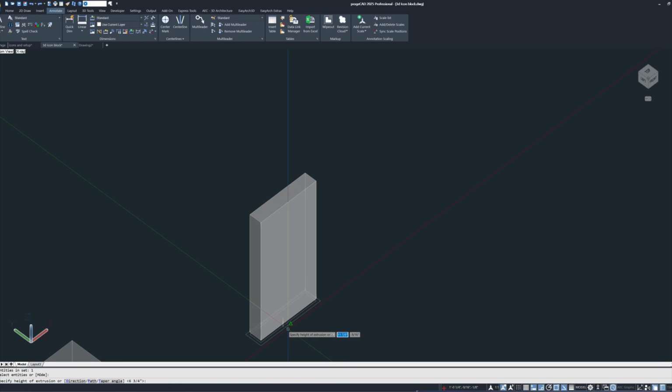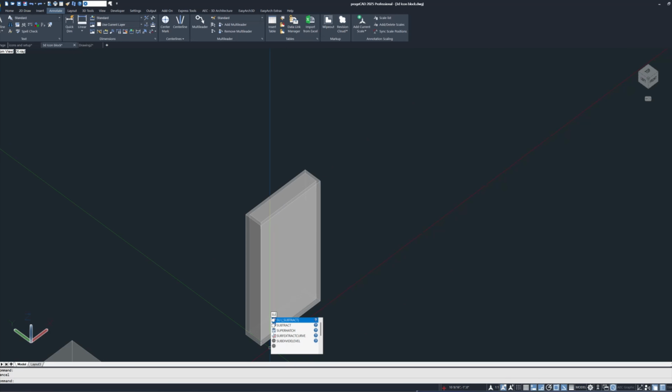The extrude command asks for the object first, then its height. I use the midpoint of the polyline, but I could have easily used the end points. Extrusions can use any easily snappable point, so long as it aligns with the height required.